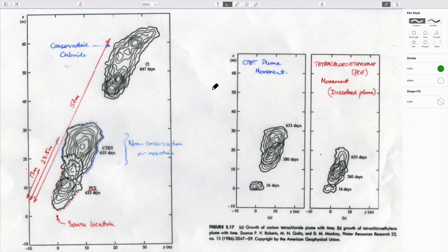It's underlain by a clay bed, so it doesn't go into the underlying groundwater. And you can follow this plume by taking capillary tubes, long, thin straws that you push into the ground, and you suck samples out to get a picture of what the concentration distribution looks like around this cloud that's going down gradient.